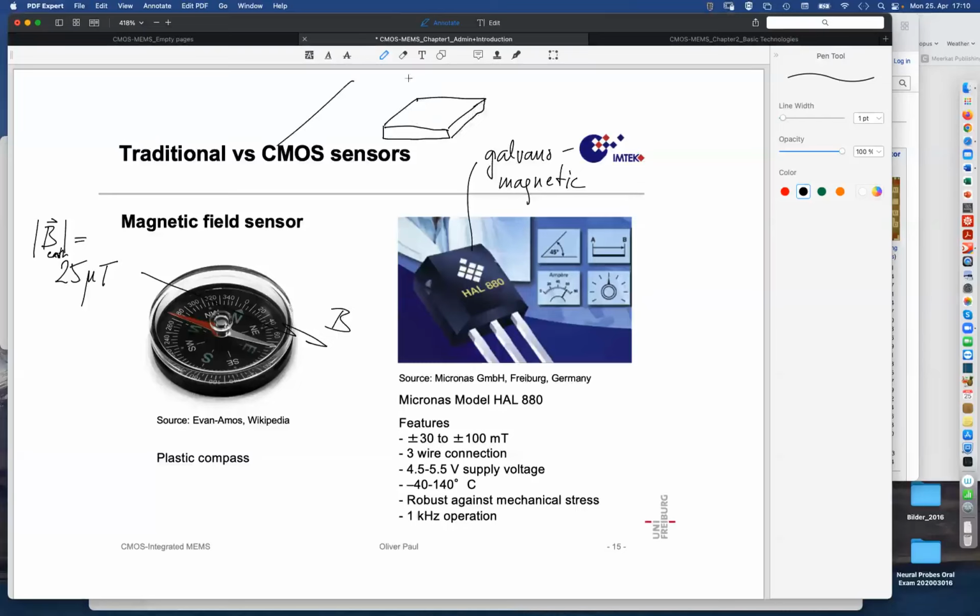So in this chip, very simply sketched here, that is embedded here with its contacts on the surface of the chip, let's say this is silicon with all kinds of circuitry all around. There is a so-called Hall sensor, which is a diffused N region, like you use also for transistors, and that has been equipped with 4 contacts on 4 sides.